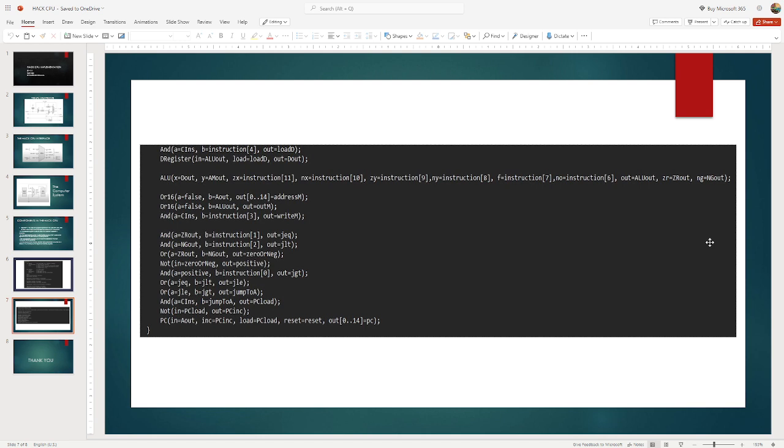The following code, which consists of two Or16s and an AND gate, sets the ALU outputs in order to successfully write on the data memory. The first Or16 code line determines the address of the write operation. The second one determines the content of the data memory, and lastly, an AND gate outputs the value that allows the CPU to write the content to the data memory.